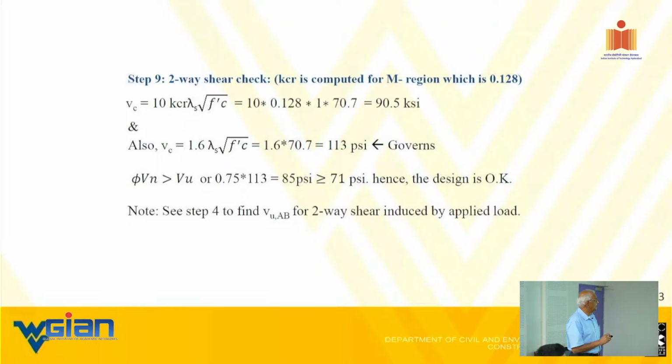This is 0.8, that's 5 for one-way shear. That is the equation given by the code. Here we had to reiterate. But here the magnitudes of shear under two-way are much lower than the magnitudes of shear due to one-way, from the induced stress point of view.